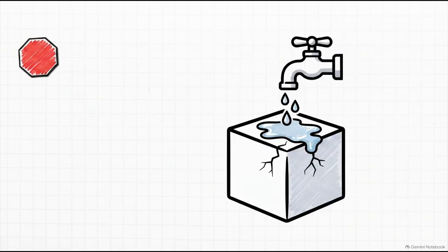That is an absolute bad practice. Now, it's true that fibers can definitely change mixture rheology and make it harder to pump, but throwing unauthorized water into the mix is never, ever an acceptable solution. It completely wrecks the water-cementitious ratio and compromises the final structural strength of the concrete. As the inspector, you must step in and halt this immediately. The mix design and the approved admixtures are what control the pumpability, not some guy standing there with a water hose.